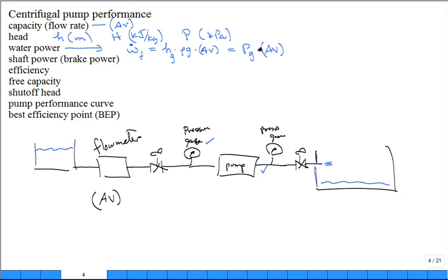It's the mechanical power put into the flowing fluid. That's what we want the pump to do. You can see it most clearly by the pressure gain times the volumetric flow rate. That product is the fluid power that we wanted to get into the fluid, right?